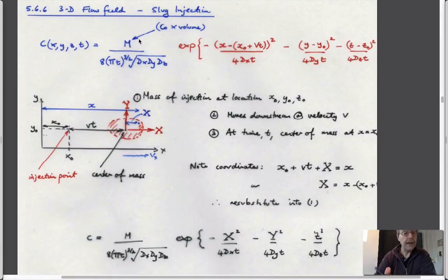So if you're looking in plan view, say you inject some water into an aquifer. X and Y are the directions in the horizontal, Z is vertical. And at some time t0, you drop this in and let it do what it's doing. It's a bit like a pebble being dropped into a pond. The water in the aquifer is carrying itself downstream. You can imagine that if you looked at this ripple going downstream, it would spread out due to dispersion. So at time t1, it might look like this.